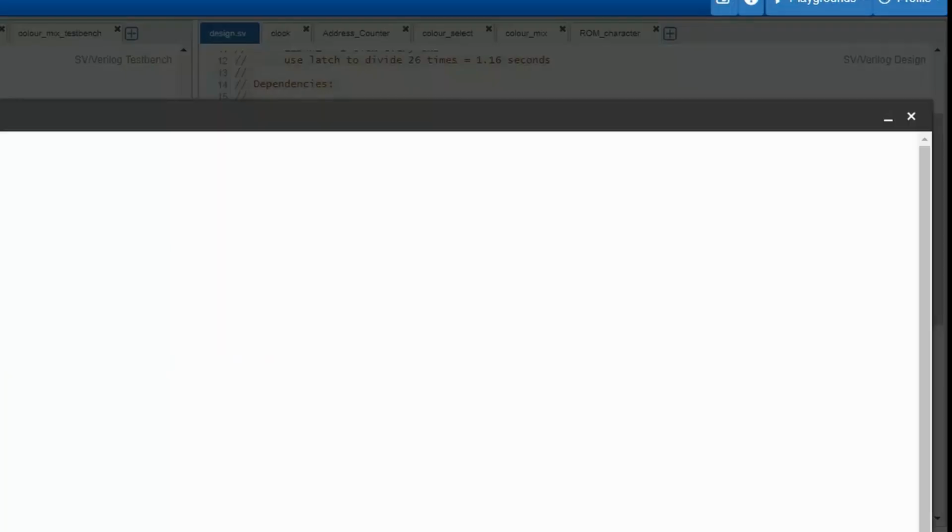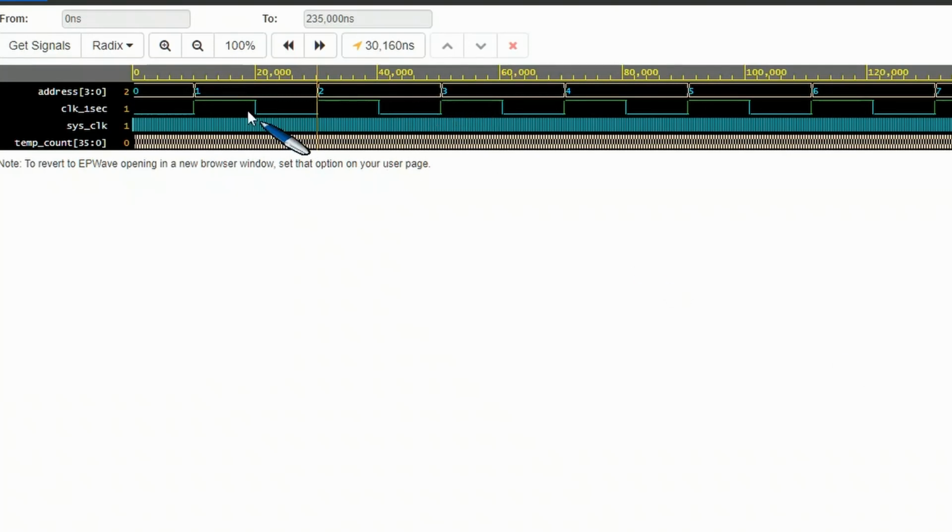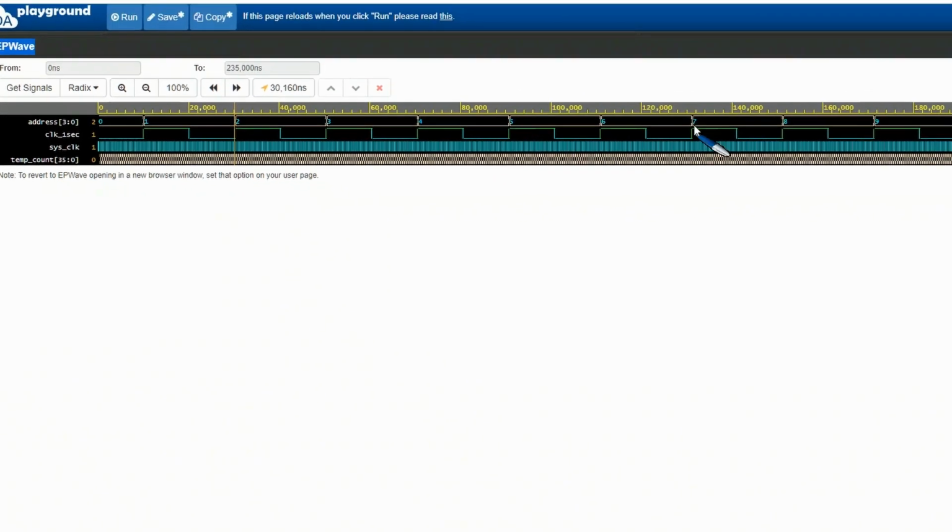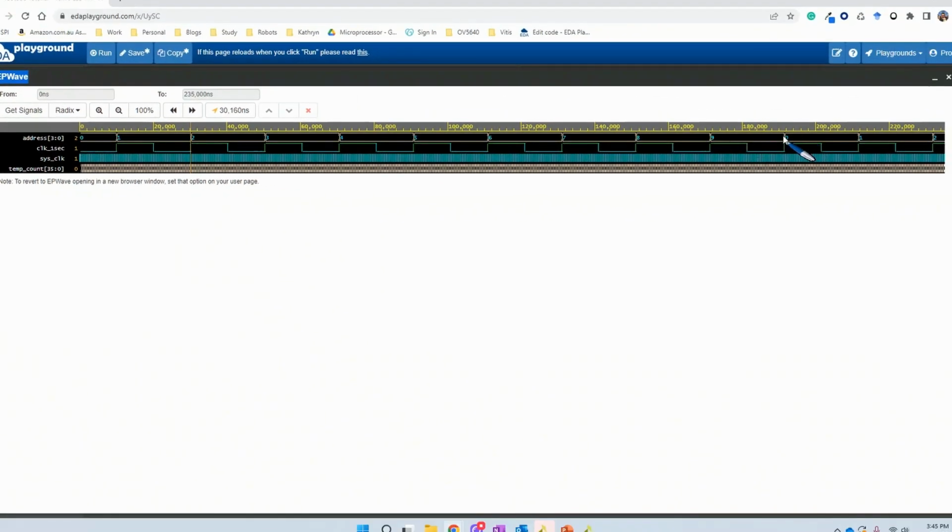So let's go back into the code, into the timing. So we can see, ignoring that error, that every time we're counting up until we get to 9, and then we're going back to 0 again. And you'll see this 0 is the full length as opposed to the first one. So it's only that power up. Ideally, we should have a reset command during power up.